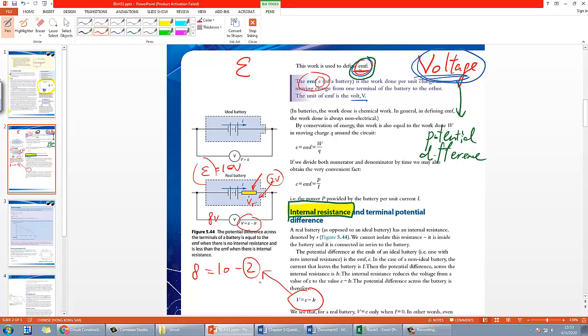The way to evaluate the internal resistance is, of course, if we have an ammeter, then we would know the I, which is the current, and so we can represent this 2 volts by using V equals IR. That's why we use IR here. Normally we cannot know how much voltage drop is on the small resistor, because you cannot put the voltmeter like this to measure the small internal resistance. It's impossible because it's inside the battery. And in fact, it is not really one piece of resistor put inside. No one actually wanted to put one piece of resistor.